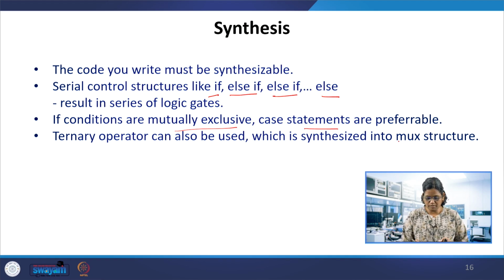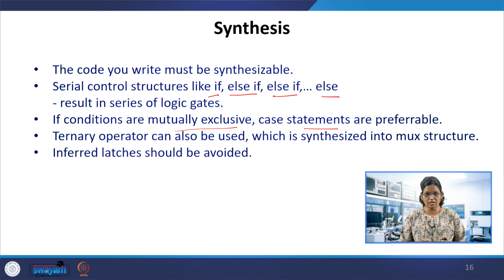In the case of an if-else statement, if an else condition is missing, it would infer a latch. We will deal with latch inference in detail when we do the synthesis of each code, and we will see how the code is converted into the equivalent synthesized block diagrams. Latch inference should be avoided in the code.